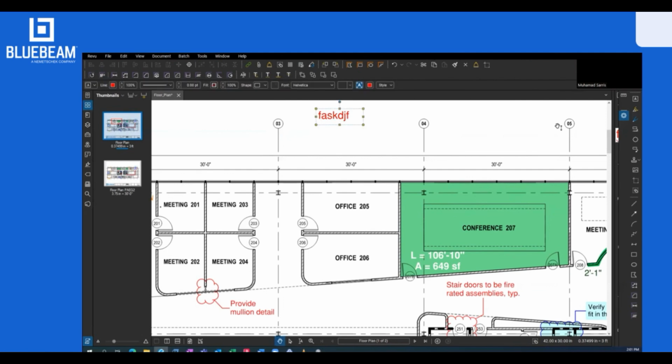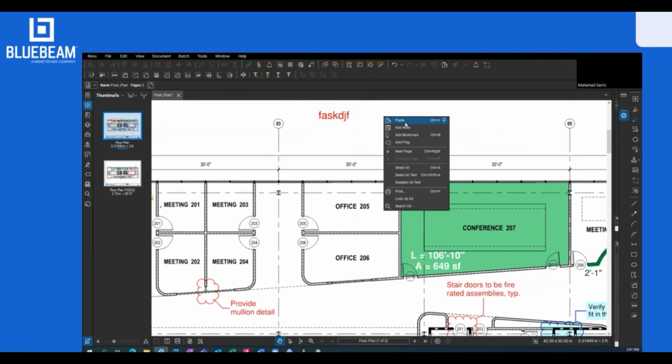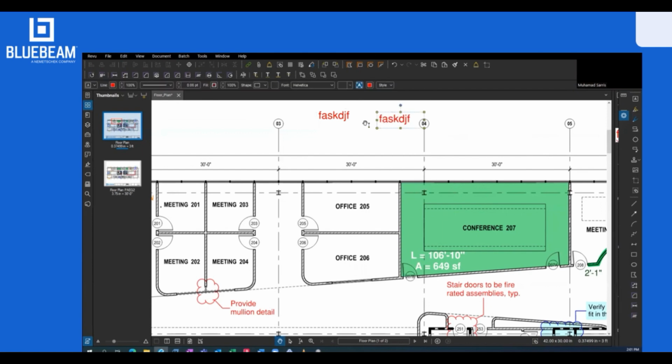Another little thing you could do is if you want to create another text box, instead of doing copy, paste, you can just click it, press Control, and then click to drag, and you can create these copies, which is really neat. So there's a lasso tool, which is Shift-O, and you can just select them all like that.